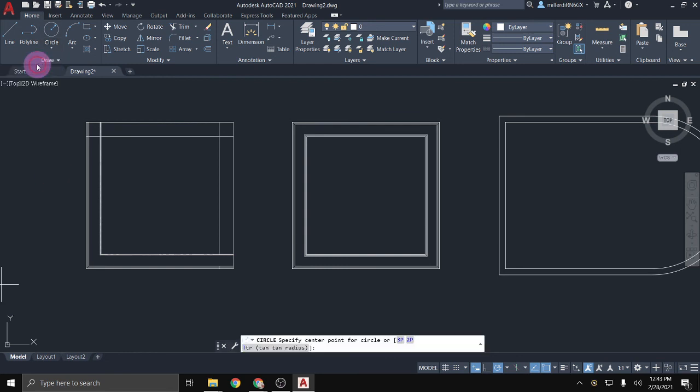So if I click on any of these options, so I just said I want to do a circle radius, the first thing my command bar is prompting me is to specify the center point of it. And then it's also giving me some of those grayed out options again. So even if I went into the circle tool and it wasn't the one that I wanted necessarily, I could still switch myself over.